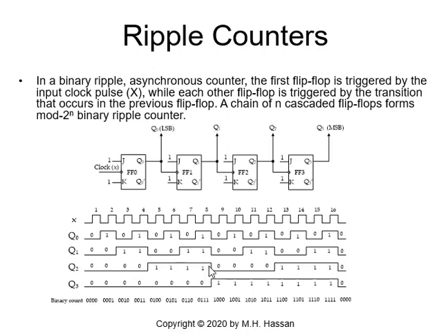The negative edge of Q2 will trigger flip-flop 3, and the output Q3 will change from 0 to 1. It will remain 1 until it is triggered again with the next negative edge, which is right here. So this is what will generate the binary sequence that we are seeking. We have 0, 0, 0, 0 at Q3, Q2, Q1, and Q0, then 0, 0, 0, 1, up to 1, 1, 1, 1. And in the next cycle, we will start with 0, 0, 0, 0 again.